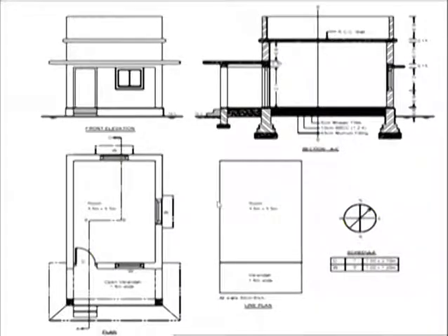Now when we cut this plan of the building with a horizontal plane, the objects or edges which are below that are shown by full line, but edges which are above the cutting plane are drawn by dotted line. You see, this is drawn by dotted line. This weather shed is above the cutting plane, so it is shown by dotted line.